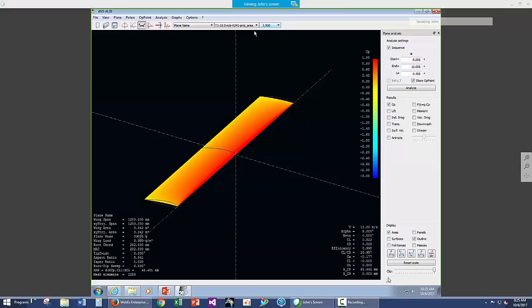At the moment, we have the CG at 0, which is at the center of the wing, at the leading edge. On the other side, we have all the dimensions that we put in. It'll always calculate the mean aerodynamic center. Trivial for this case, we've got an aspect ratio of almost 6. Notice it also calculates the neutral point for you. So this is, as Professor Kahn talked about, the location of the neutral point.